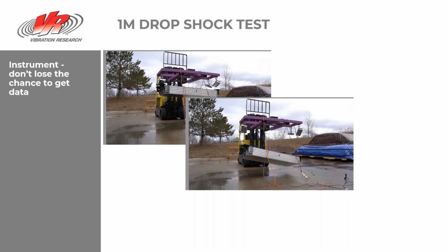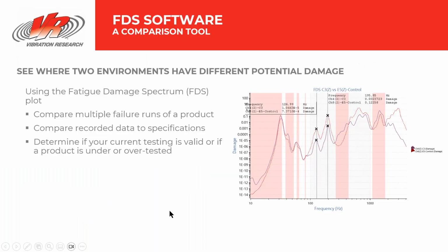That might be something people should look at when doing battery drop tests. Because if you hit a corner you're going to get local deformation, but if you get a true flat drop on the base of the battery pack, the shock is far greater because there's less deformation. So you've not got that crumple zone to reduce the shock level.